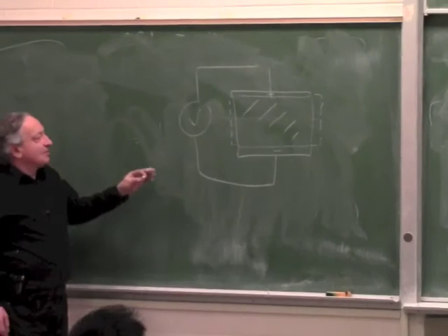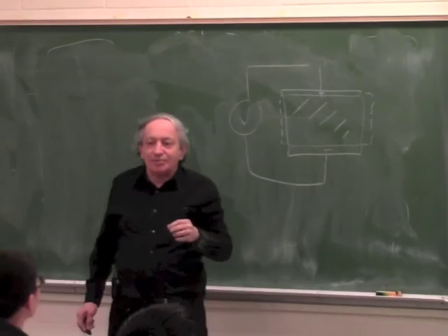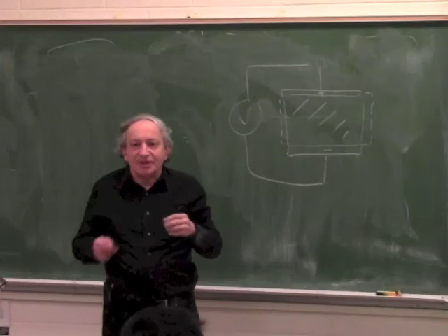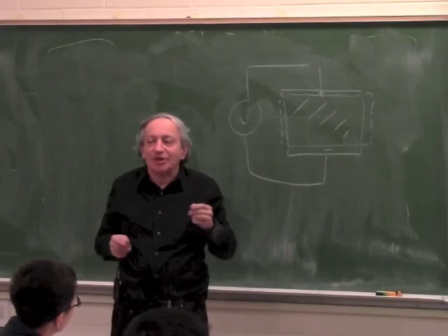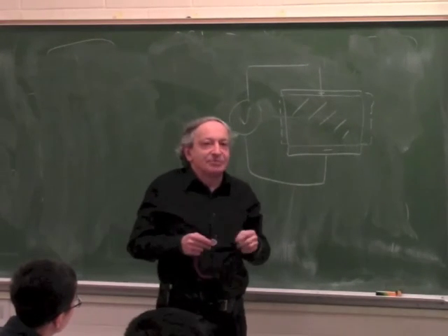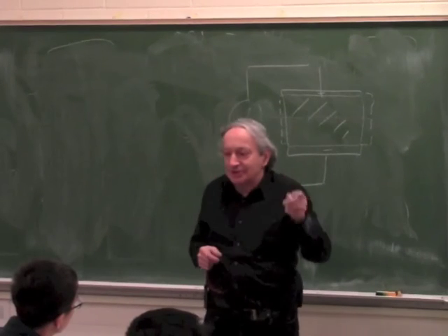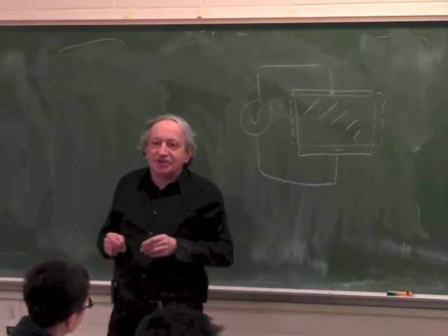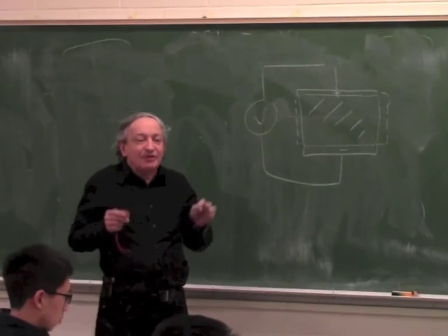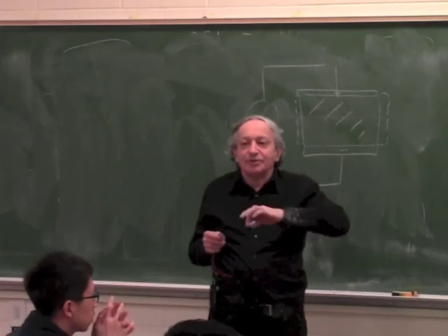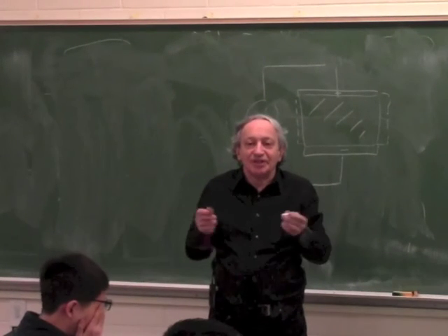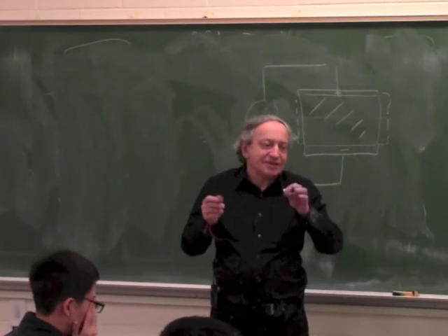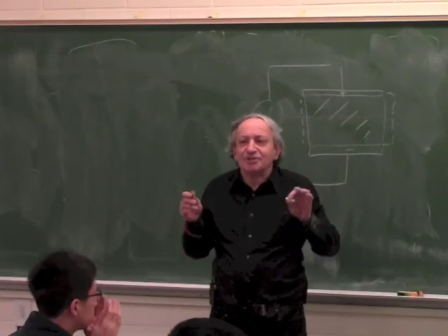Now this is a bit similar to magnetostriction. I mentioned before that if you take a magnetic material, put a coil on it, it will shrink when you apply a magnetic field. That's the reason power transformers make noise. I mentioned it many times. But magnetostriction is very simple. Whenever you put a magnetic field, it doesn't matter which direction, it always shrinks in the direction of the magnetic field. It doesn't depend on crystal structure. It's a much simpler story.